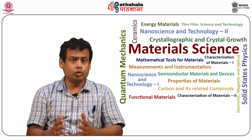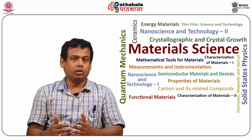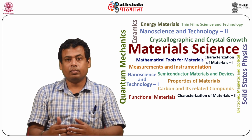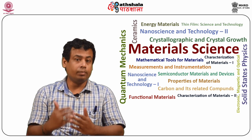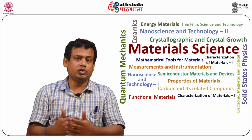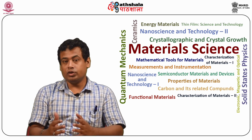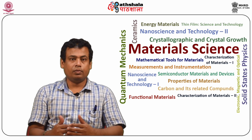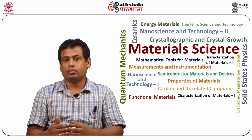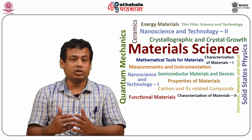Lithography provides an advanced tool for designing structures at micro nanometer scale by patterning on the surface of various materials. It allows the interaction of electromagnetic particles with organic and inorganic molecules, and subsequent chemical dissolving produces features of sizes in the order of the incident wavelength. Photolithography utilizes photons for patterning at hundreds of nanometers, and higher energetic sources of electron beam are utilized for designing structures at tens of nanometer scales.